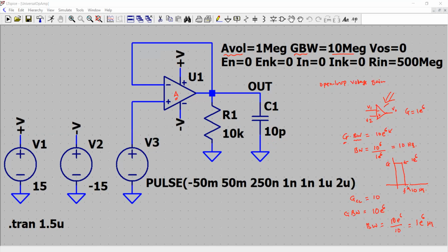So in that case, your frequency response can be drawn like the gain is now 10, just a 10. So it would be like this. Let me draw this, and this is your x-axis for the frequency. But now you see, the green curve indicates your response of an amplifier. So gain is 10, and the frequency right here is 1 into 10 to the power 6. So 1 megahertz, signals having the frequency up to 1 megahertz, you can apply to amplifiers